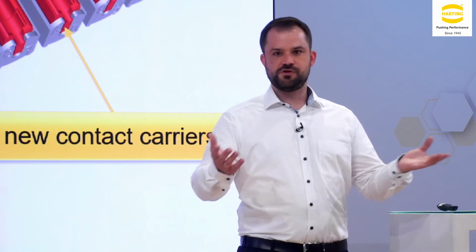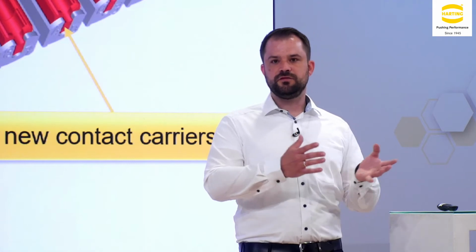So in the first 3 categories, you can have 4 connections, and in the category 8 channel, you can have 2 connections. This is something that you have to keep in mind when building up your shielded connection: if you want to reach Cat 8, then the number of connectors is limited within that channel. The use of the different categories ranges from private networks, like at home, where often Cat 5 is used.